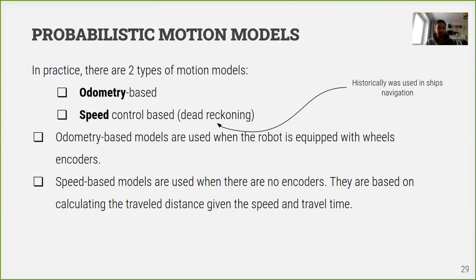So a typical car is equipped with encoders, and once again they're used to estimate wheel rotation, so how many degrees our wheel was turned, and having that data we can estimate speed, obviously, because knowing how much we rotated in time, we can integrate and get speed of each wheel, and having speed of each wheel, we can also estimate distance traveled by our car or our robot.